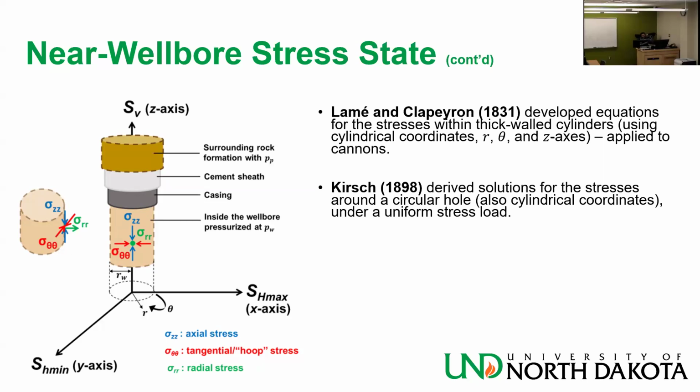He took Lamé and Clapeyron and imagined a hypothetical problem of a 2D plate with a circular opening, with stress applied on the opening, tension, the same way that you apply wellbore pressure, basically.